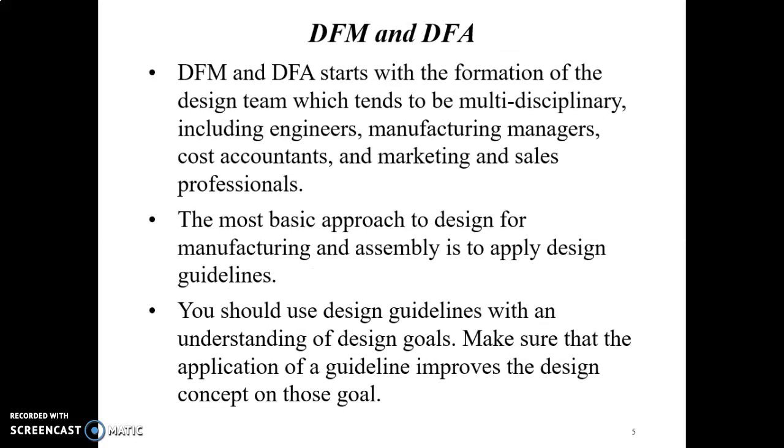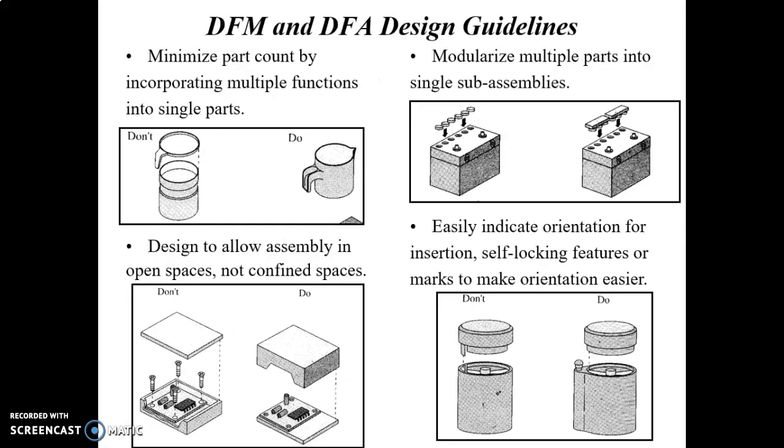Okay. DFM and DFA start with the formation of the design team, which tends to be multidisciplinary: engineers, manufacturing managers, cost accountants, and marketing and sales professionals. So it will start with the management first. This person will lead to decide what type of DFM and what types of DFA they are going to implement. The most basic approach to design for manufacturing and assembly is to apply design guidelines. You should use design guidelines with an understanding of design goals. Make sure that the application of a guideline improves the design concept on those goals.